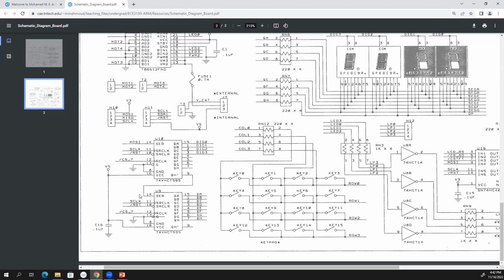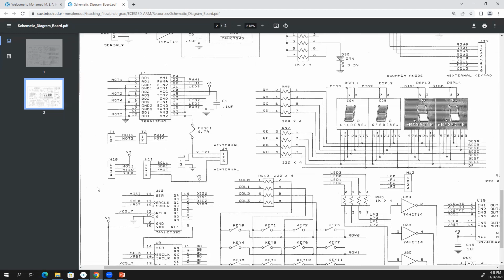So because of time multiplexing, we can reduce the number of pins from 28 to 12. And now I can even reduce it more, from 12 to only 3. If I cancel this part, I just connect it directly here. I need 4 pins here, and I'm going to connect it directly to the microcontroller.